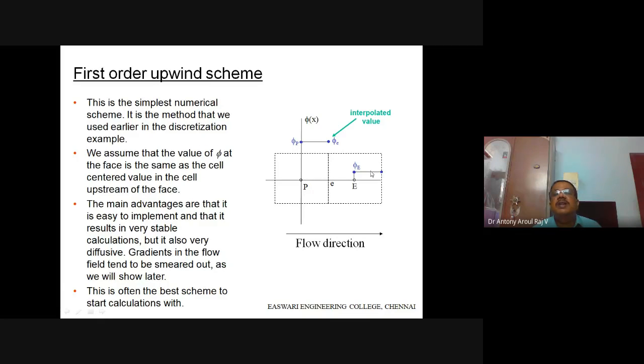What the upwind scheme does is, for any face, it takes the upwind value only. No averaging business. For this face, it takes the upwind value; similarly for this face. For any face, it just takes what is there at the left hand side. Now, what is the advantage of this? The velocity information is at the left hand side, and you are giving priority to that side. Because of that, the velocity information will go into the domain immediately. So your scheme is good and it is safe. That is what we call the first order upwind scheme.